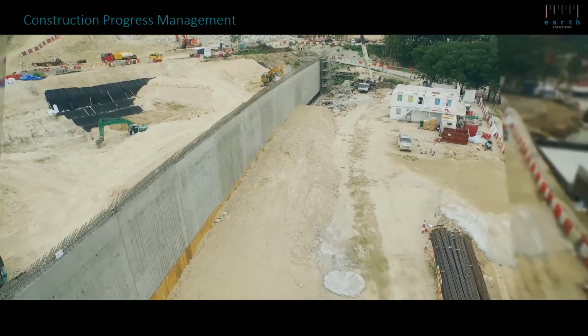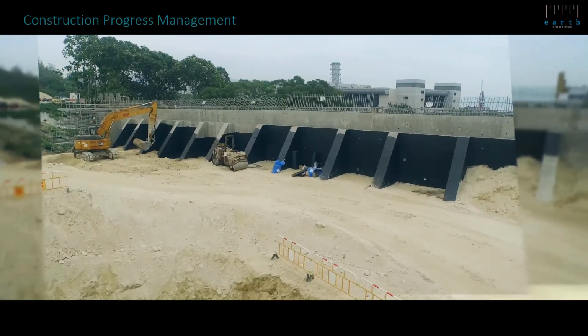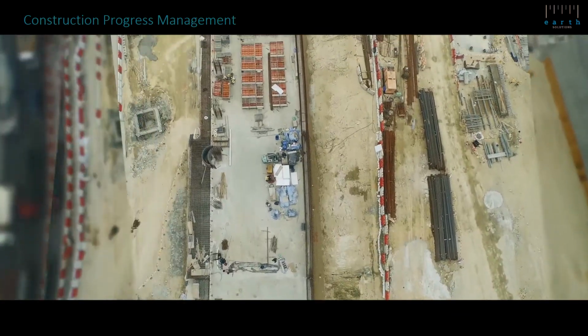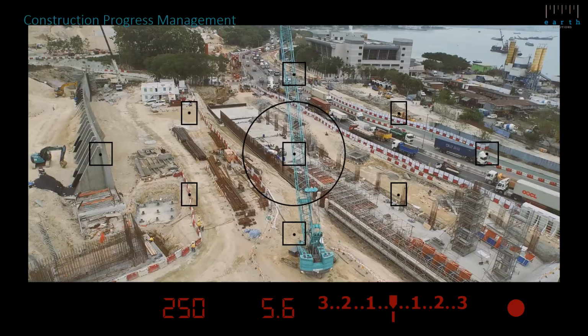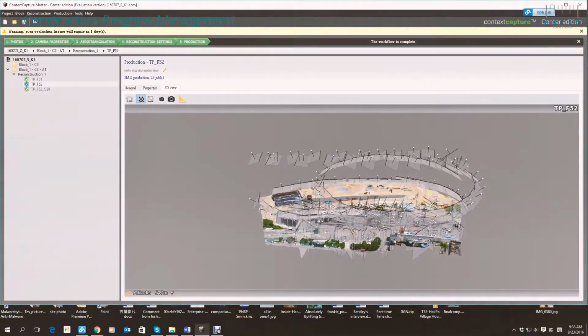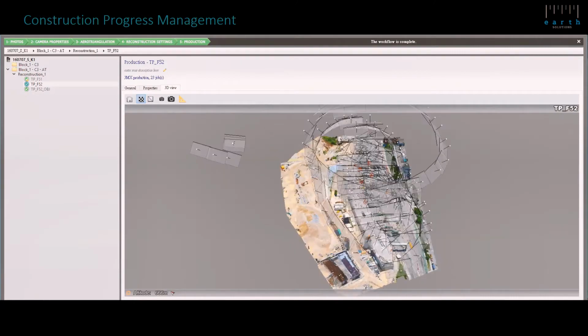Here we see video from the drone. These are the straight down nadir views that are being taken. And while it's moving around, it's taking incremental pictures, making sure that they have enough overlap to create a 3D model. Here we see the final product. You can see where the photos were taken, so we see our back and forth nadir images as well as the orbits.